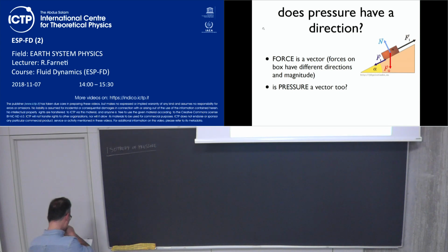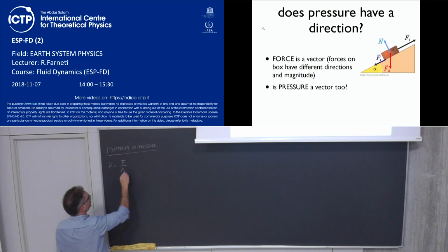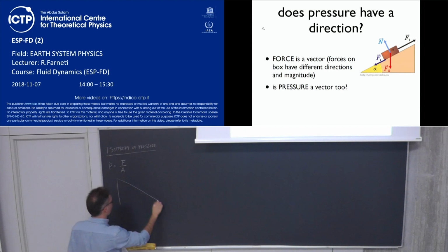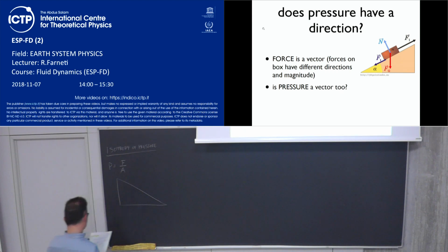Okay. So pressure is a normal force, okay, per unit area. So we have pressure, which is a normal force in a static fluid per unit area. Okay, that's the only force acting on the fluid. So if we consider an infinitesimal point, okay, how does pressure vary with the orientation of the plane? So we can have a simple example of this kind of shape, where we have some delta x, this is going to be a delta z, and it's unity in delta y into the board.